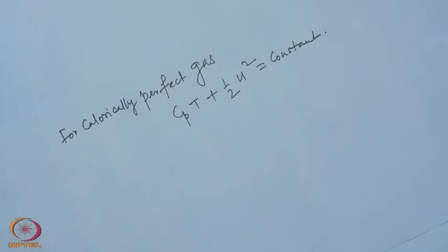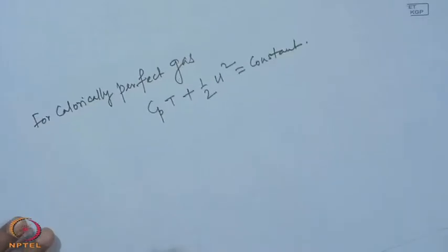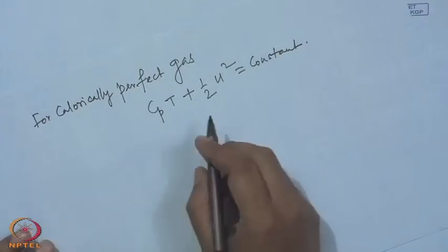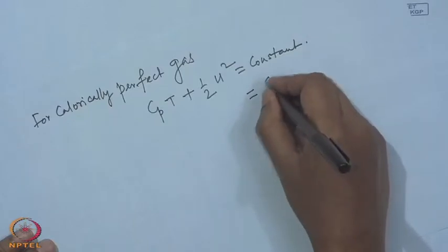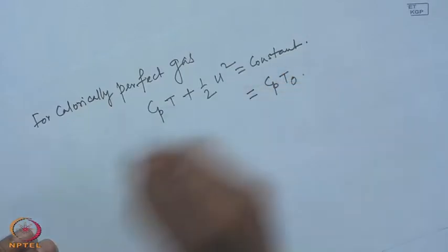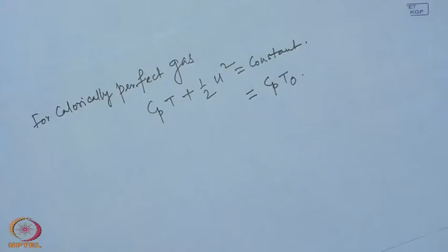And again if u equal to 0 and the fluid is uniform, similar to stagnation enthalpy, we get stagnation temperature or reservoir temperature. Reservoir temperature or stagnation temperature, as well as reservoir enthalpy or stagnation enthalpy, can also be called the enthalpy or temperature of a reservoir where the flow velocity is practically 0 and in which no heat transfer is taking place.